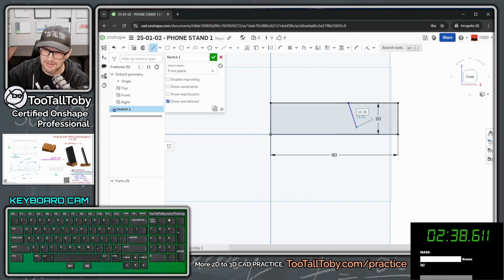And here's what you want to get used to. If you're practicing sketching, get used to automatically adding in that perpendicular relationship. So you can single click here, move up this way. See how we're automatically getting that perpendicular relationship? The more practice you do and the more of these relationships you get on the fly, the more time you're going to be able to save. So we'll single click here, and now we're done with the line command, so we can press escape.